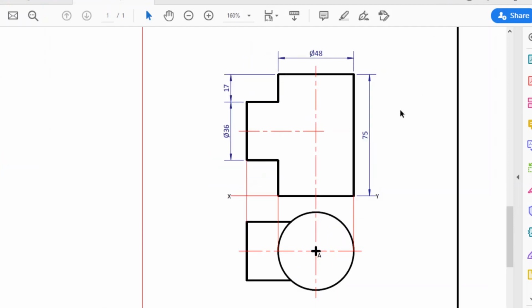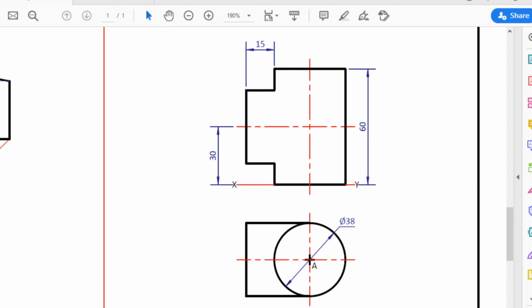Then just to recap, the front view is sitting here, and the top view is sitting there. So obviously, this is in first angle orthographic. And if we look at the grade 11 page, it's the same thing. The top view is below the front view, so this is also in first angle orthographic projection. Both are on scale 1:1, so no change to the measurements on your page.